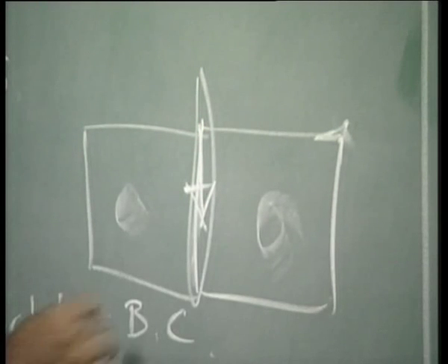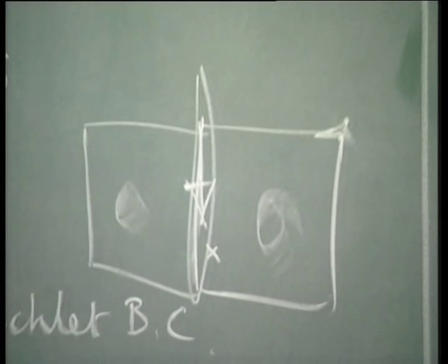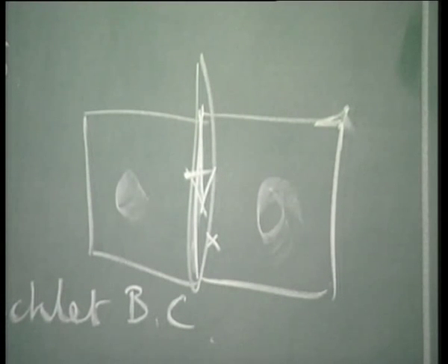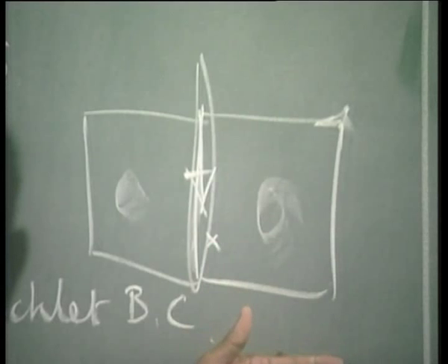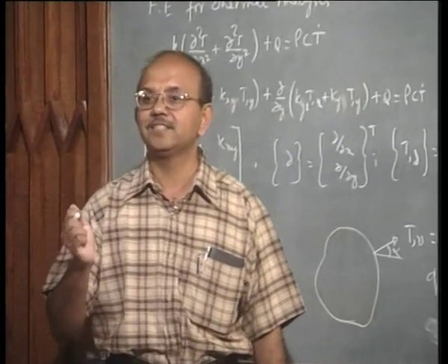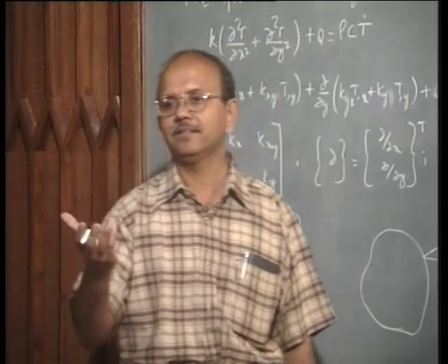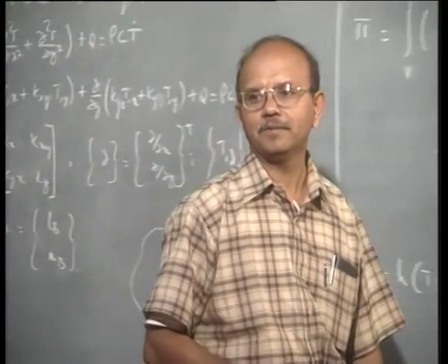Obviously, when I am sitting here monitoring the temperature, initially I am not hot, and as this weld pool moves towards me, what is going to happen? My temperature is going to increase. So it is a question of the temperature being a function of time. Obviously this is not a steady state problem, it is a transient problem.